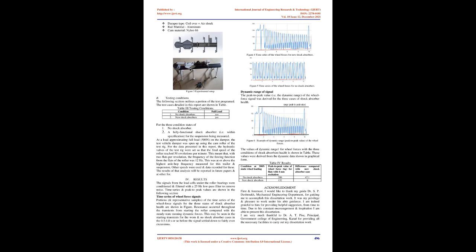Acceleration response for different values of sprung mass is plotted in the figure. It can be observed from the figure that the passive suspension gives better comfort for maximum sprung mass. However, as the sprung mass reduces, higher acceleration deteriorates vehicle comfort. Figure 2: Sprung mass acceleration for different values of sprung mass.